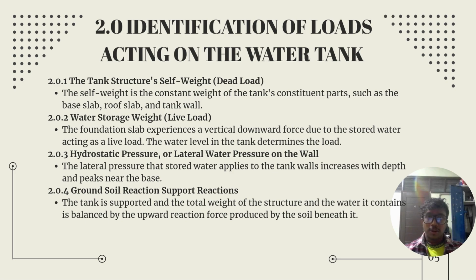I'm going to talk about the identification of loads acting on the water tank. Firstly, the tank structure's self-weight, dead load. The self-weight is the constant weight of the tank's constituent parts such as the base slab, roof slab, and tank wall. Secondly, water storage with live load. The foundation slab experiences a vertical downward force due to the stored water acting as a live load. The water level in the tank determines the load.